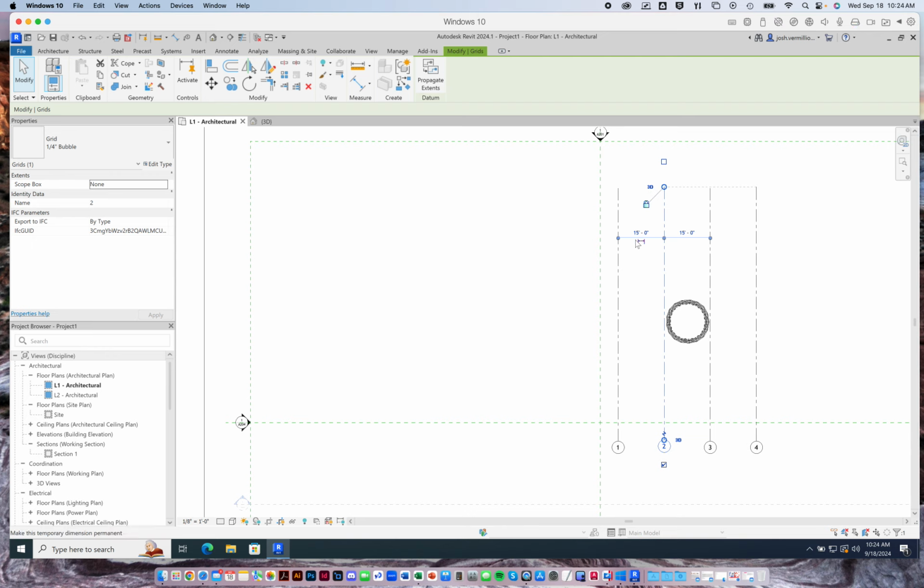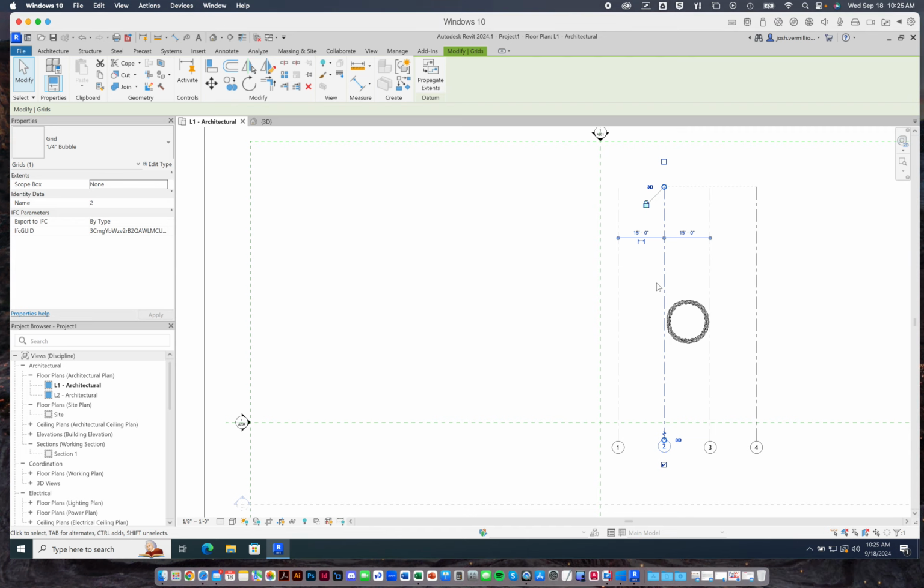All right. And it's the same thing here. There's ways to begin to constrain these things so that, let's say I always knew I wanted a 15-foot increment, but I think that the edge might change, right? I can make all of these things move along with this one. Or I could say unlock those and then start to move them independently from each other, right? So there's ways to build some of these associations in.